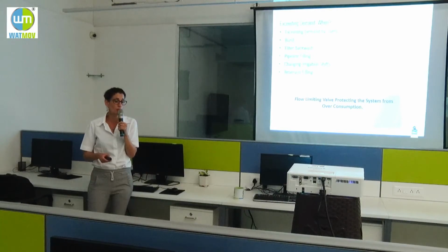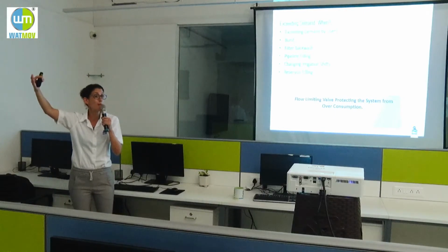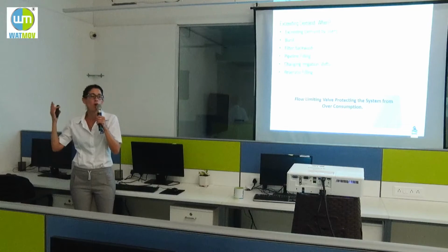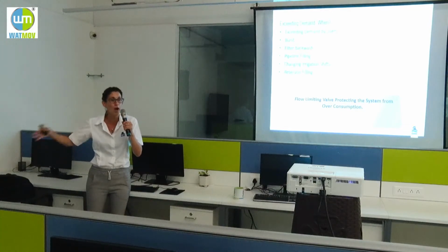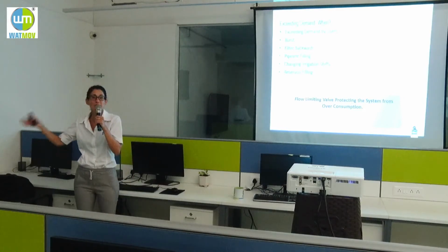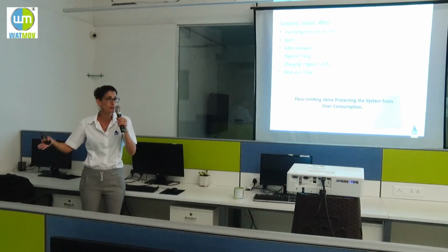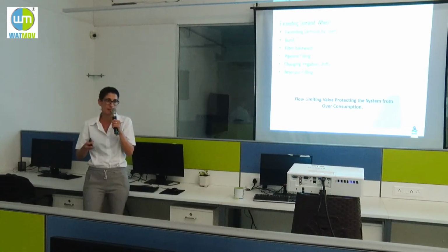So this is important, but we can overcome this issue like we did in package 21. We can calibrate the flow setting 30%, for example, above the design flow. So only when there is a colossal case, something really went wrong, someone stole the OMS, the automation doesn't work, okay? A burst happened, then we will regulate, okay? Only in colossal cases.